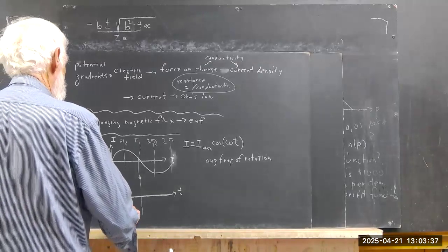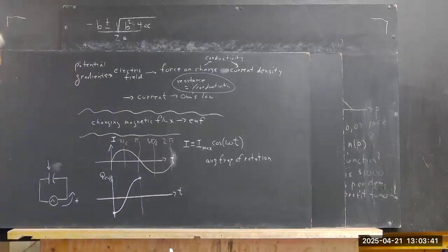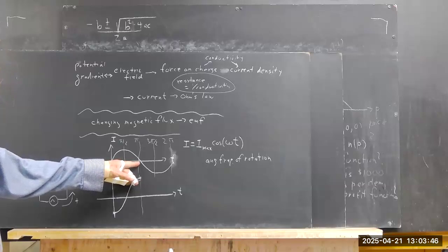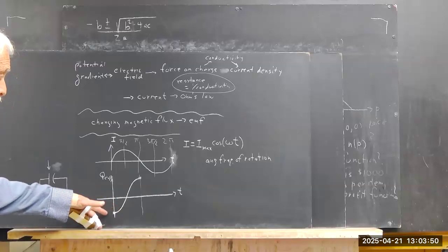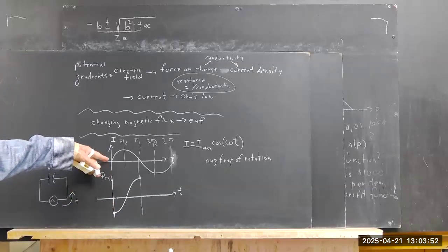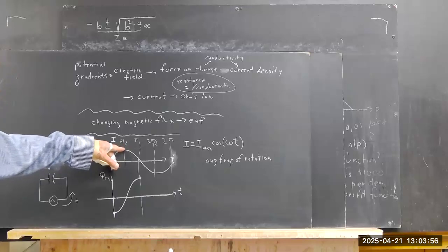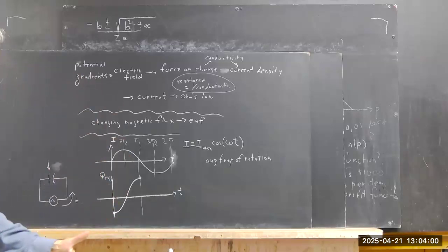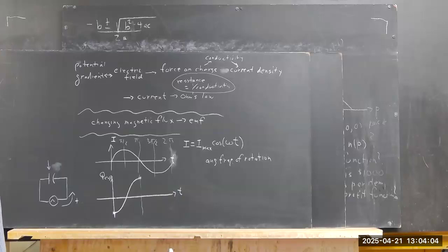So this phase, when you're pushing charge onto the capacitor, here it is. It starts out not building very much because you don't have very much current. Your current maximizes here, so you're pushing charge onto the capacitor at the maximum rate, which means your charge is going to increase most rapidly there, okay?